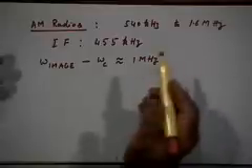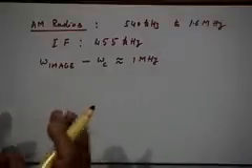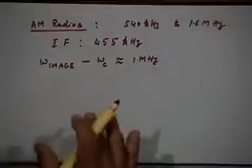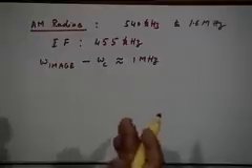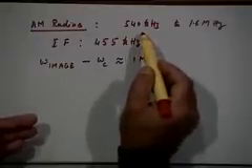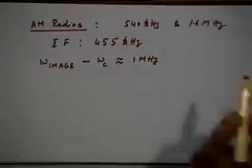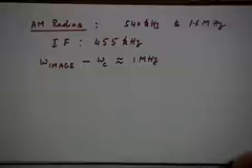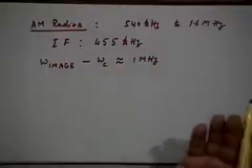Now you require very moderate selectivity, hardly any selectivity. You are saying that when the 540 kilohertz signal is coming in, the 1.54 megahertz signal should not be allowed to pass through the RF filter. This is hardly an issue. It can easily be done. Designing such an RF filter which is tunable and providing this kind of selectivity is not an issue.